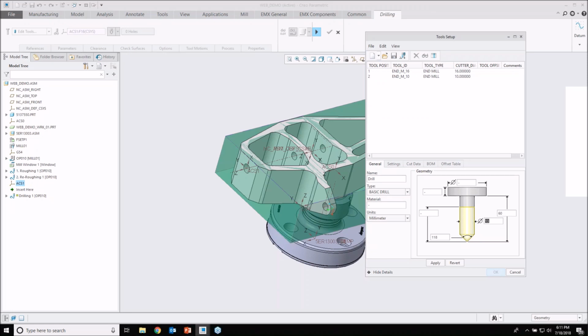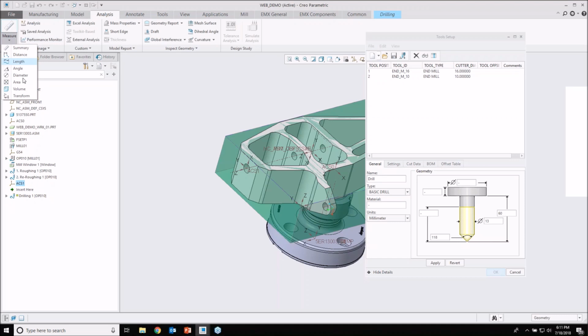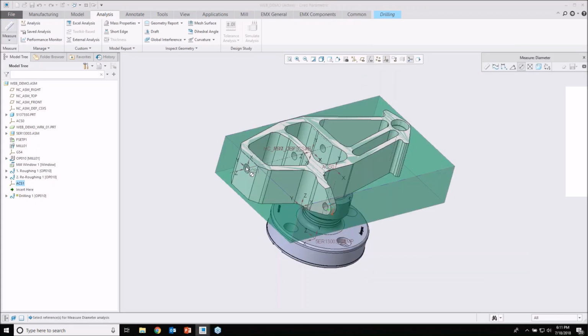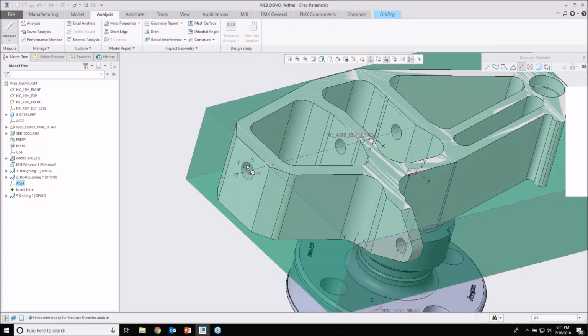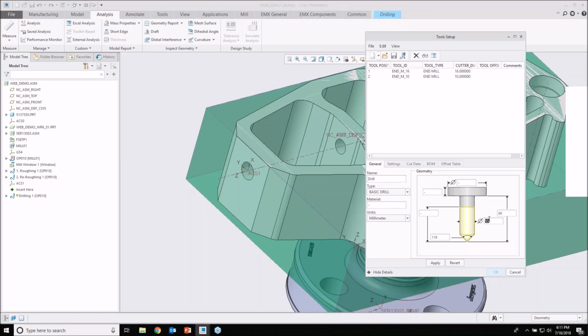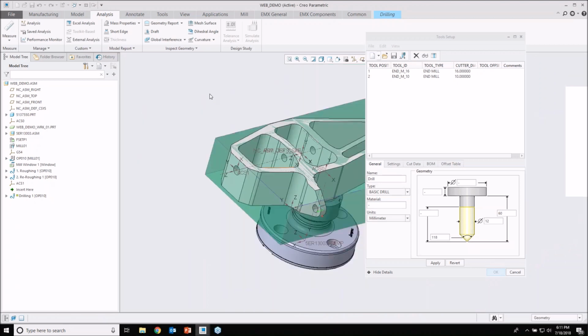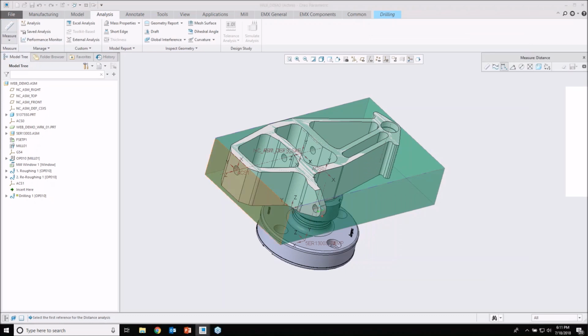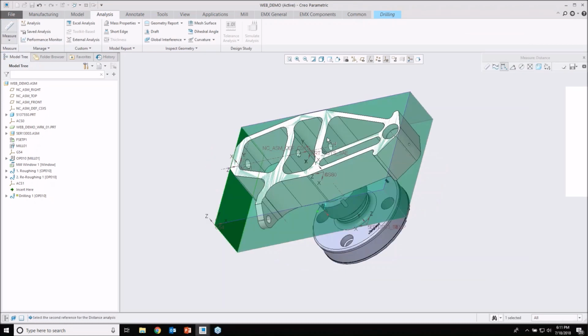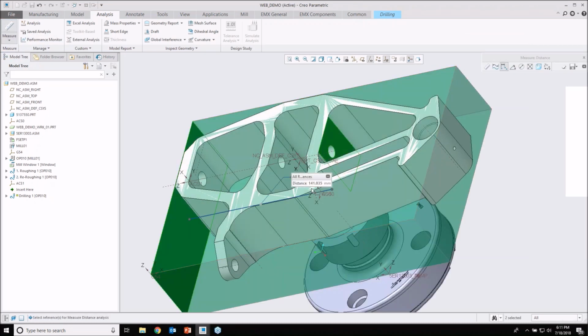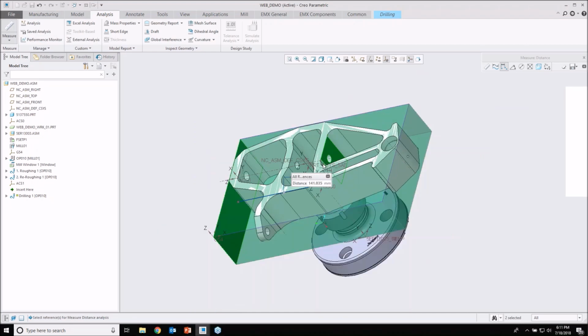And I can't remember that hole diameter. I think it was... let's quickly measure it again. 12. Okay. Then we're going to use a 12 drill. It needs to be fairly long, so let's measure that as well. From this surface there, 140. Yeah, that's deep drilling.